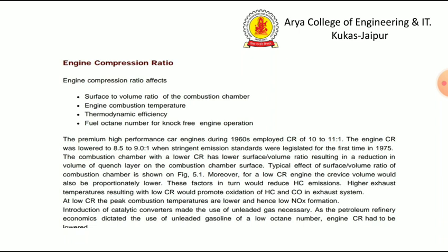The effect of surface to volume ratio of the combustion chamber shows that there is reduction in the HC emissions. Moreover, for a low compression ratio engine, the crevice volume would also be proportionally lower. These factors in turn would reduce HC emissions. Higher exhaust temperature resulting from lower compression ratio would promote oxidation of HC and CO emissions in the exhaust system. At low compression ratio, the peak combustion temperature is lower and hence NOx formation is low.